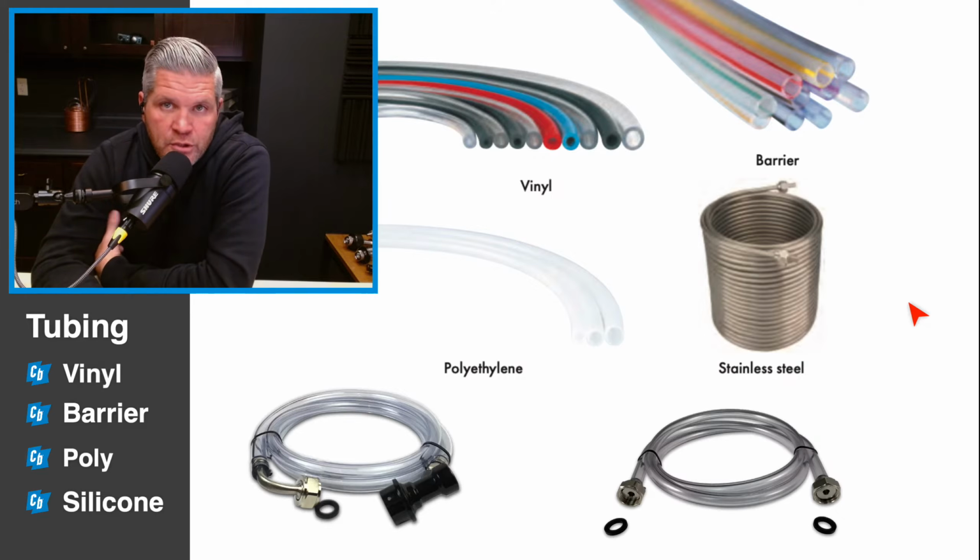These lines are usually made out of different materials. Vinyl is the most common for jumper lines because it's soft, it's flexible, it's easy to maneuver. That's typically connected to barrier tubing, especially in a long draw system. Barrier tubing is very hard, rigid plastic and has a very low resistance. And so you can push beer through here at a great distance with very little resistance.